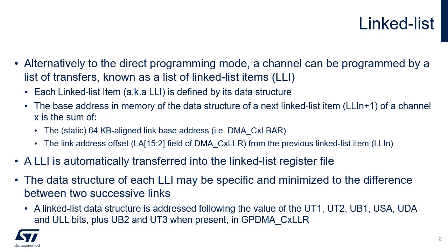However, the same channel can only be reconfigured when the ongoing transfer is completed. In order to decouple software preparation of transfers from their execution, the linked list approach is more convenient. Each item in this linked list is called a linked list item or LLI. The LLI is mapped in memory and contains an image of the values to be initialized into the DMA channel registers. Thus, DMA channel registers programming becomes an indirect operation.